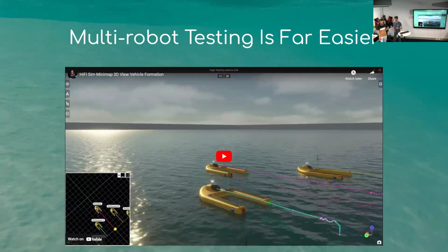But you touch on something that I would like to specifically note here. For the kind of simulators that we've been making, it's far better to get information about the real behavior and then tune the simulator to model that real behavior than it is to try and suggest what the real physical behavior is going to be directly from the simulator. That's because you're making a lot of assumptions and simplifying a lot of things in order to get things working in real time. So it's easier to go the other way and get a good result than it is to try and get the simulator to be perfect and then use that to make assumptions on how the physical properties of the vehicle will behave.